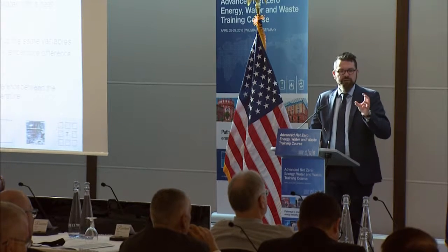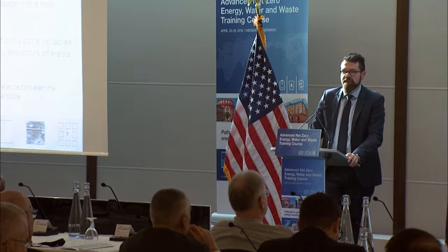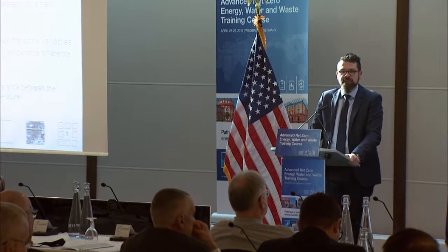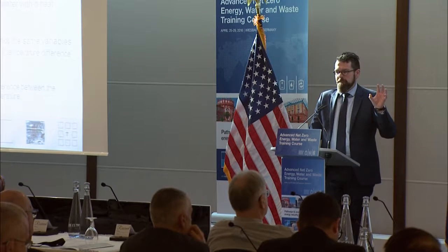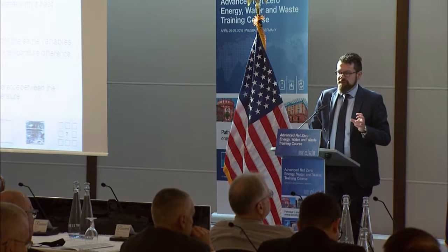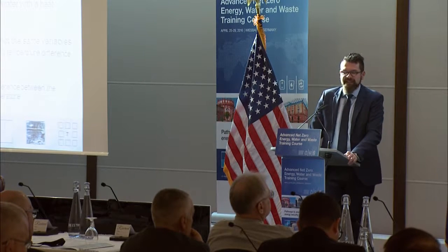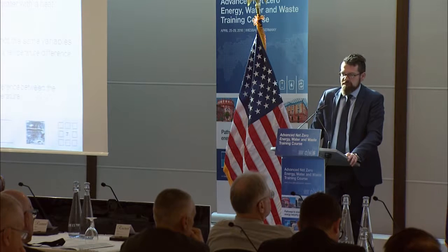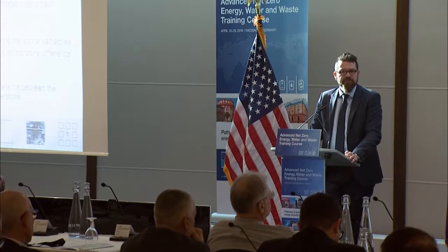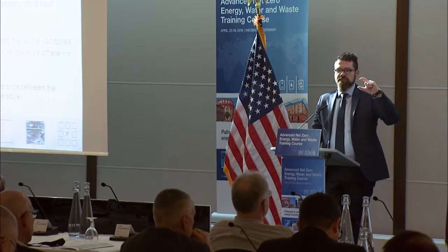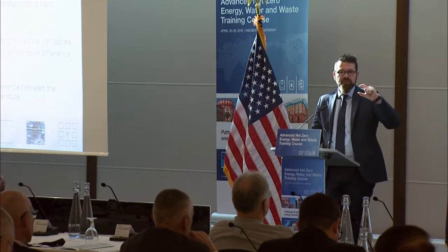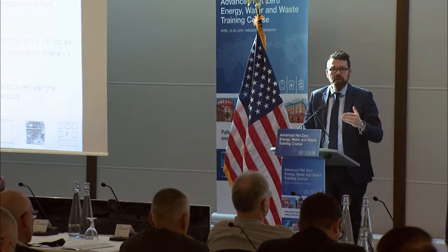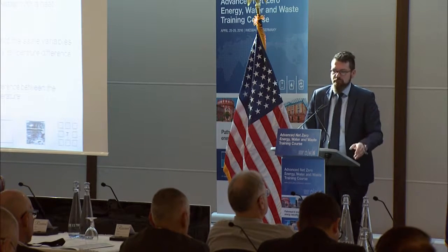The heat energy we need to meet the demand is, in case of hot water systems, the mass of water or the amount of water, a physical description of the heat capacity, so the amount of heat water can store, and the temperature difference between two different temperature levels. For instance, the temperature you supply to the building and the temperature you have in the room, or the return temperature when you bring the water back.